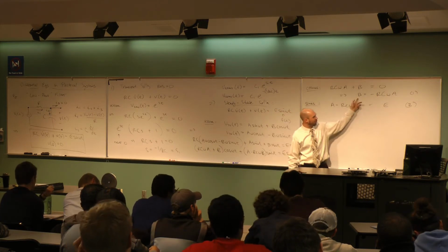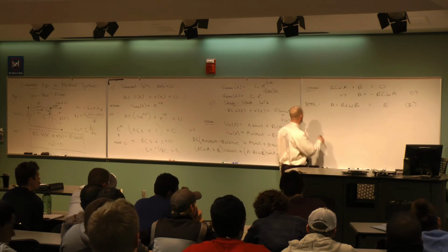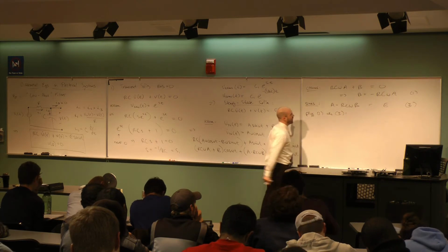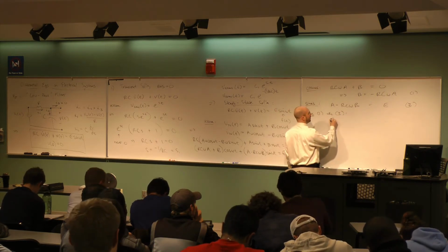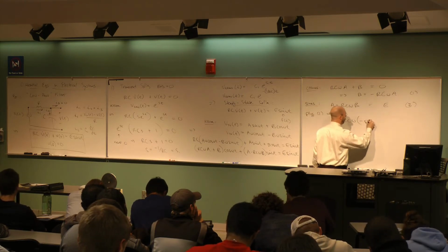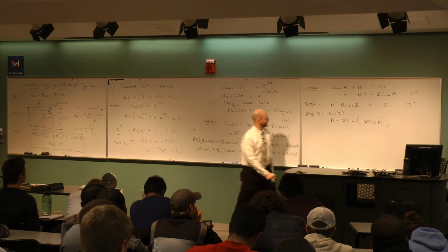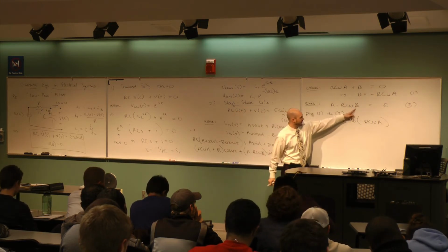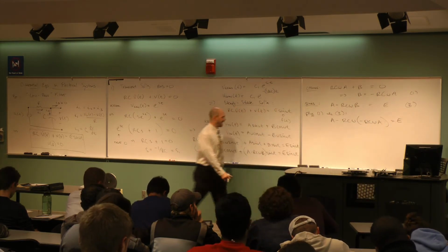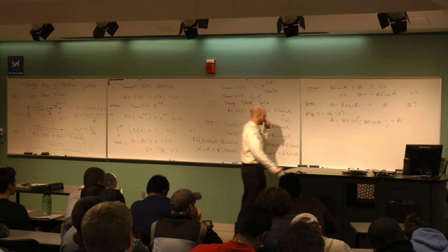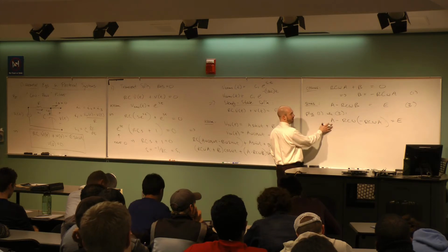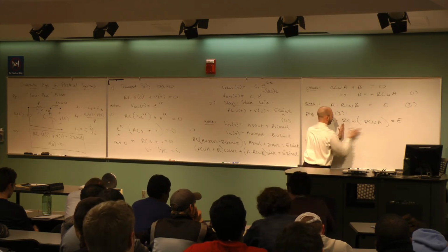And so, look, this is already B in terms of A. Can I just plug 1 into 2? Plug 1 into 2 and see what you get. All right, and so if we do that, it's going to be A minus RC omega times B. Well, B is minus RC omega times A. Just plug it in for the B right here. This is equation 1. That equals E. And then again, you got to be a little comfortable with your algebra. What can I factor out of these two terms? The A, right? This is all one term. This is multiplied. There's two terms.